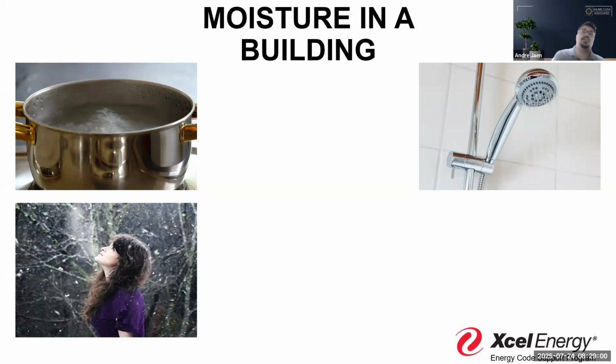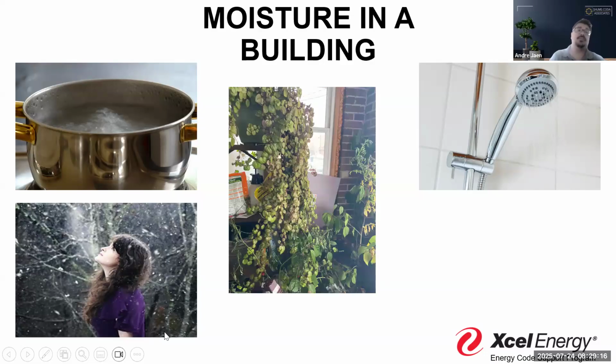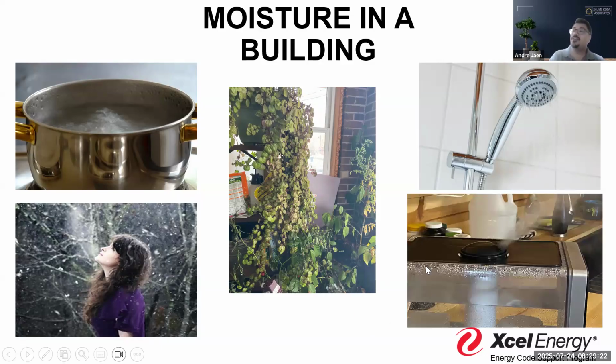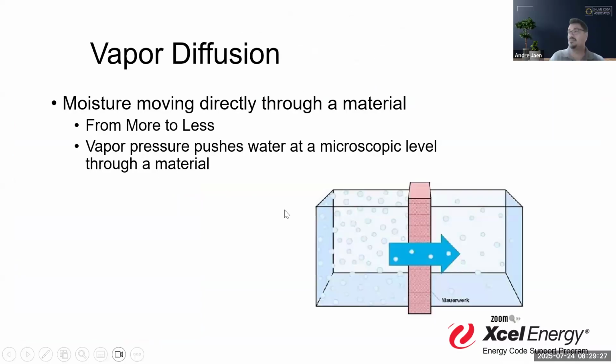Your Manual J tests your furnaces at 50% relative humidity. And so it's important to recognize that you're always going to have a little bit of moisture on the inside of this wall assembly. We also like plants for the most part, right? Or we have pets. We have other things inside the house that are also going to create moisture. And there's our humidifier, for instance, right? So that's a creature comfort issue.